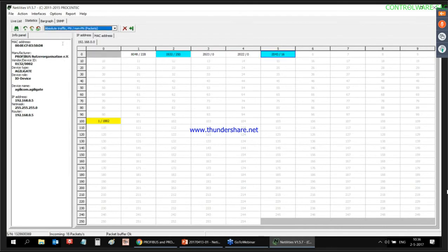The absolute traffic of Profinet compared to non-Profinet, you can see that here. And blue means that it is updating or changing the value. So apparently this device has sent no non-Profinet packets at all, only Profinet. So the first part is Profinet and the second part is non-Profinet.